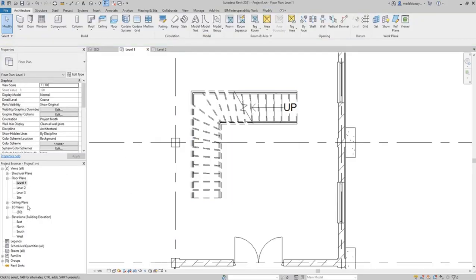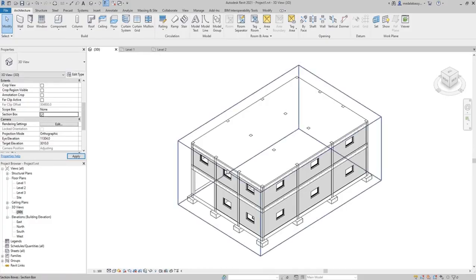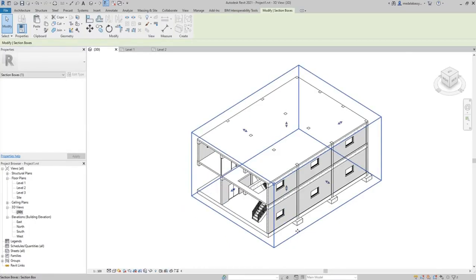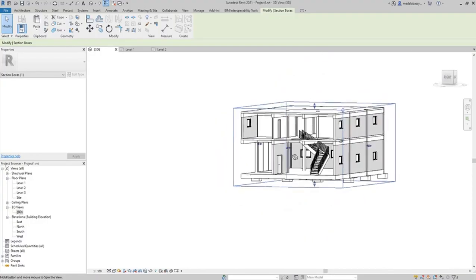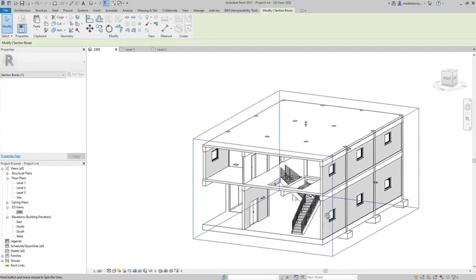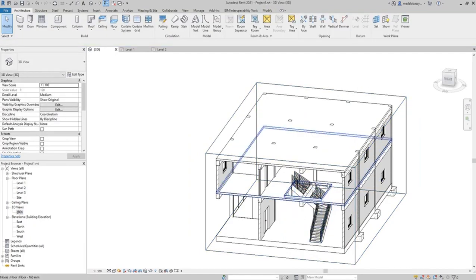If you check in the 3D view again, this time I'll just use a section box, it's easier. Click on it and drag the handles a little bit in, and now you can see here, if you use the shift and the scroll to view it, we have the staircase and the shaft modeled. So we'll draw the railings for the second level and then fix the beam.